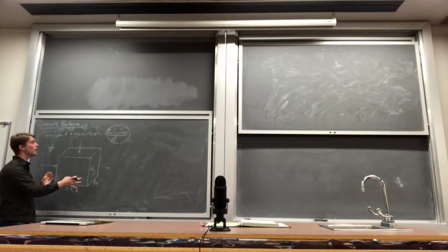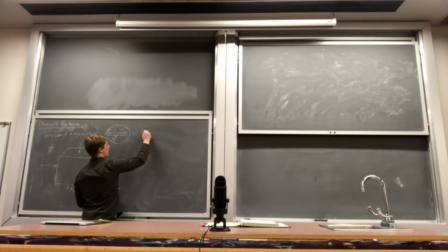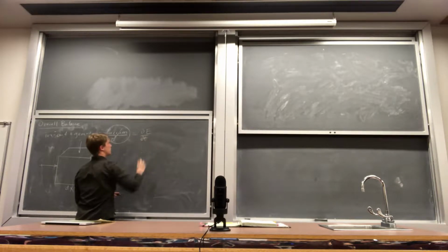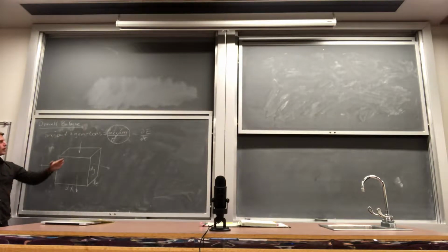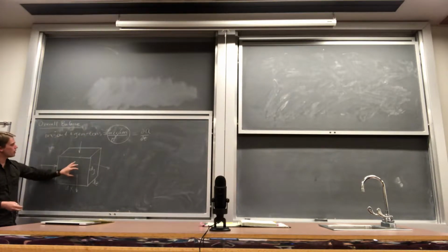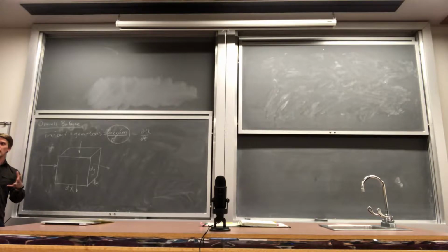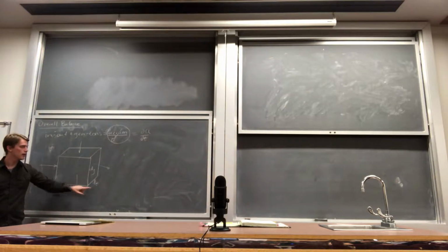Now, if we apply this concept, the accumulation term in the case of mass and energy balances, let's say is dm, actually let's say dE dt for an energy balance, okay, because that's what we're talking about. So the total energy, better write that as U, the total energy coming in and out of this particular process here is going to be proportional to the material properties. This is going to be proportional to the temperature difference. And this is essentially then what you'll be accomplishing in the heat transfer class, is to reapply everything that we've done in this class, but shrink it down to a box of dx, dy, dz.